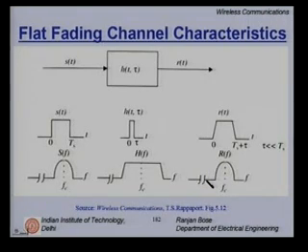However, suppose I would like to decrease my signal symbol duration. I can do that. Today we are pressing for faster and faster data transmission, which forces us to reduce Ts. In that case, we will have a much broader h(t, τ), maybe multiple impulses here, and then you will see that the situation changes. We will talk about it.